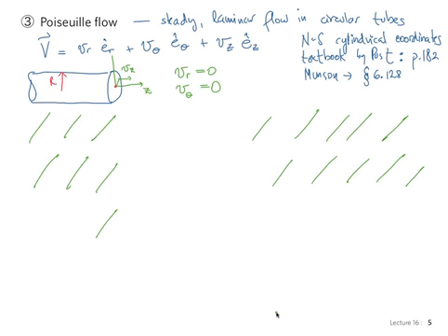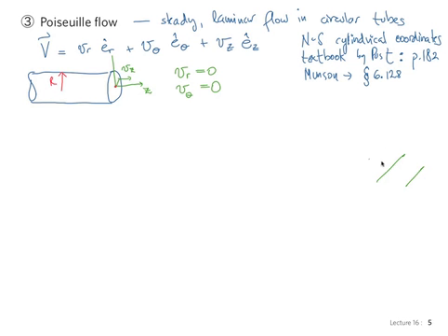So my equations disappear. You saw it's the same process that we used before, and you can see that the equations look awful, but the symmetry allows us to simplify them quite a bit, and this is how they look after the simplification. In the r direction we have 0 equals minus rho g, and we're going to write immediately the component in that direction of g multiplied by the sine theta, minus dp/dr.